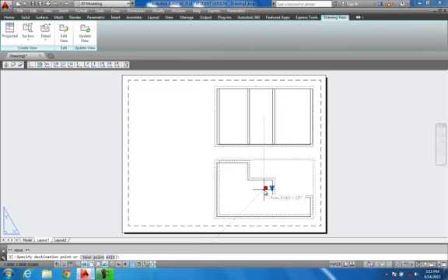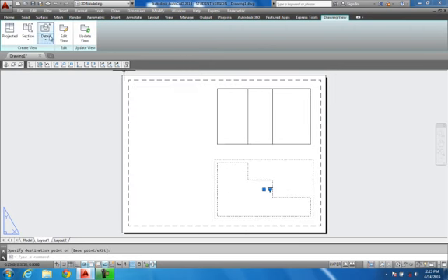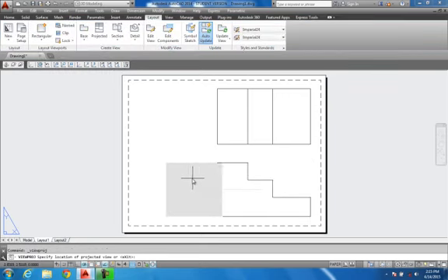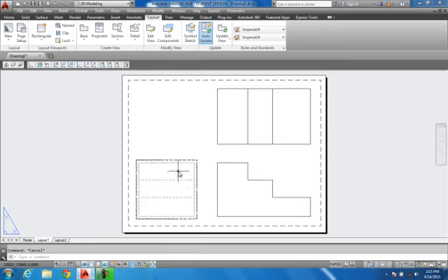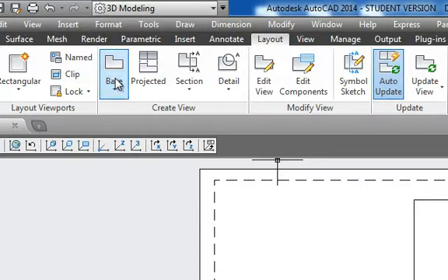But now I want to do a project. I want to put a left side view just so that you can see how it puts in the hidden lines for you. Pretty sweet. So it's very rare that you ever put a top, front, and left side. Most of the time it's right side, but also I'd go in there and do a base view,